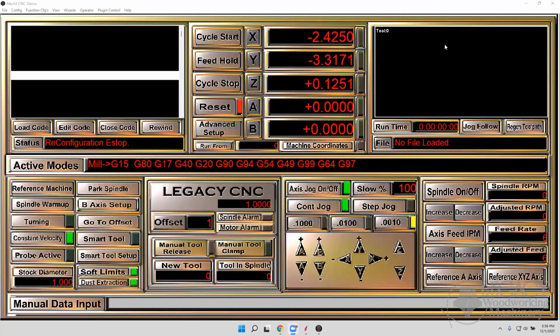Okay, how do you copy one offset to another, e.g. offset 6 to offset 7 in Mach 3? All right, I'm going to share my screen again. Let's say that we're in offset 1 right here. I'm not going to use go to offset unless I zero my Z up high. And then I can say go to offset.